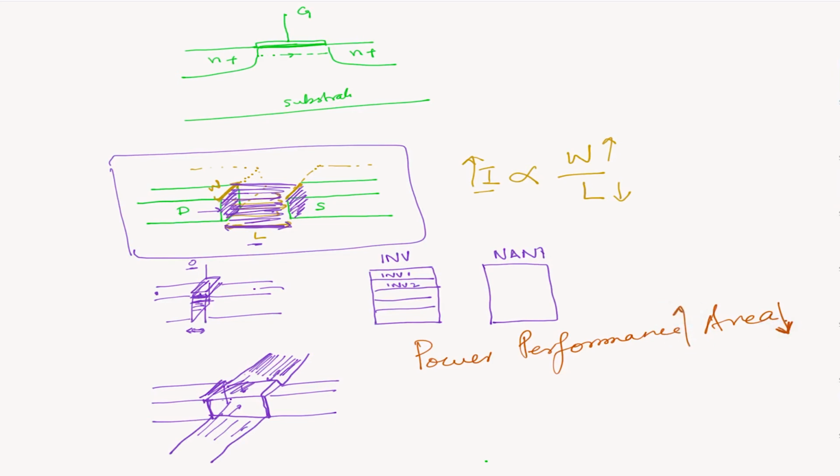Performance is the frequency, I mean how fast the circuit runs. We want to make it faster and faster. Okay, so we want to get much higher performance. And in the power, you want to have as little power as we can, because when more power dissipation happens, your die will get hot. You need to have more cooling mechanism on the board. So PPA, these are the three factors that we really want to optimize on our circuit.